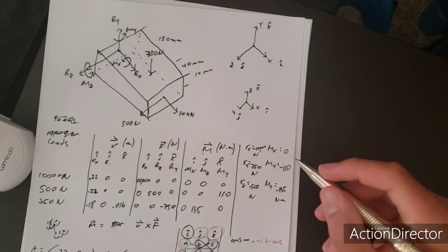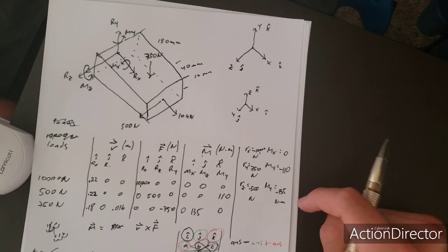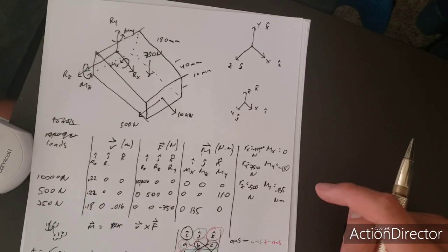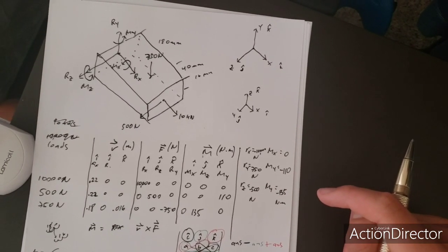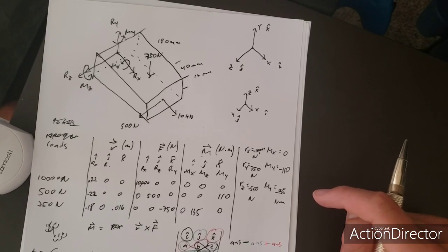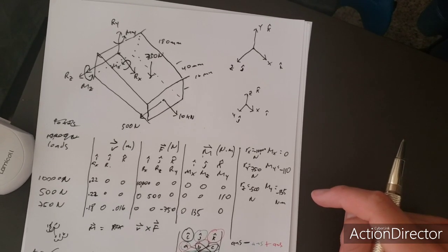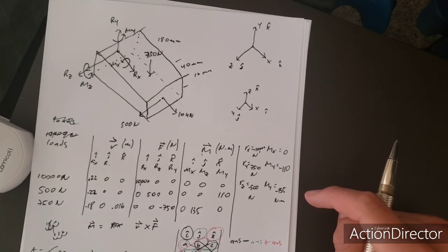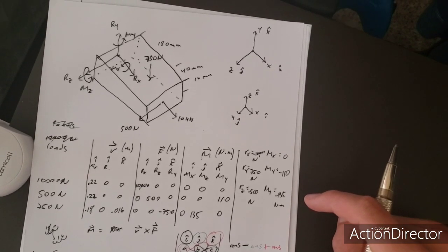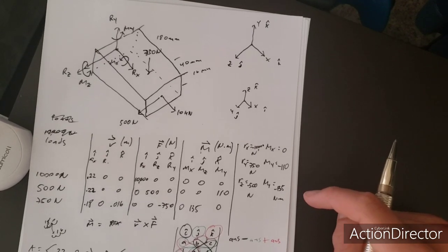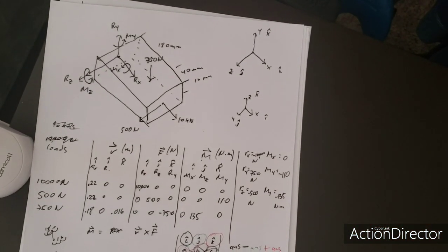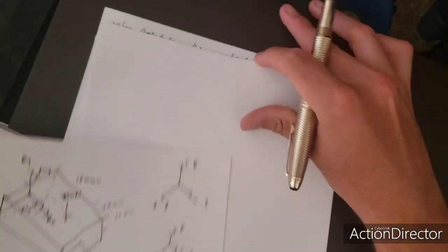Okay, now I can do the stress blocks, so that then I can add all of the stress blocks. I do all the stress blocks combined, and then plug into the principal stress formula to find what are the maximum stresses I can have on every possible plane through a point A. Okay, let's see.